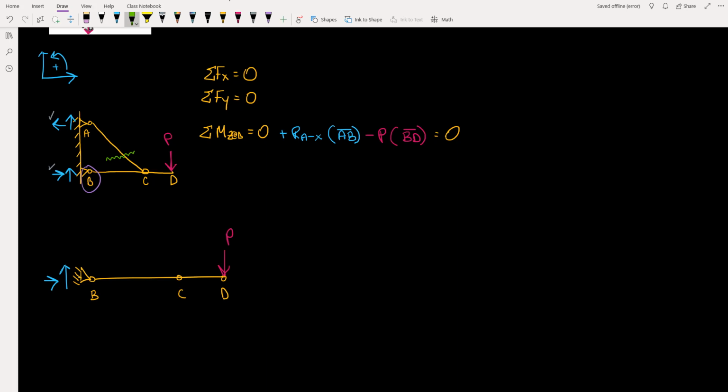So there was some internal force in this member AC that we need to apply to our cut free body diagram below. So that force is going to be an axial force, because this member is pinned at either end, and so it's either going to be a force in this direction or in this direction. In other words, it's a tension force or it's a compression force.